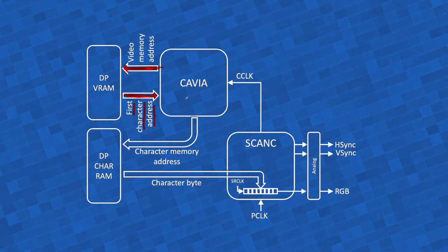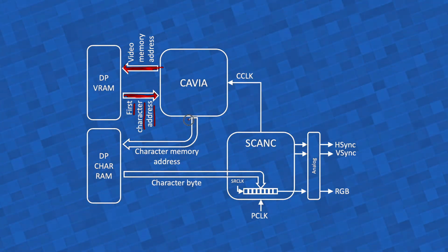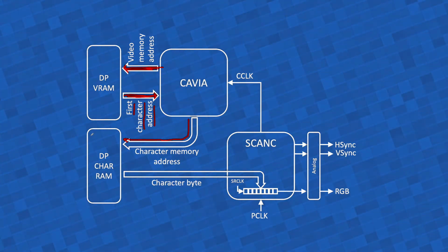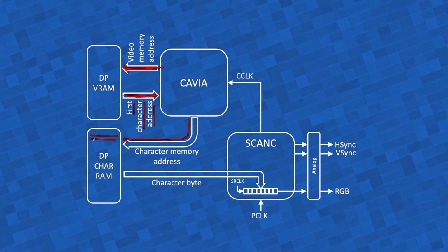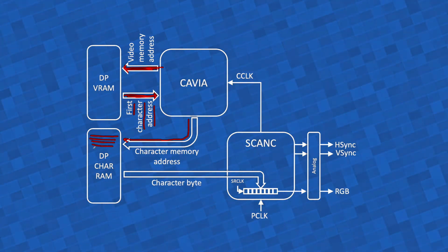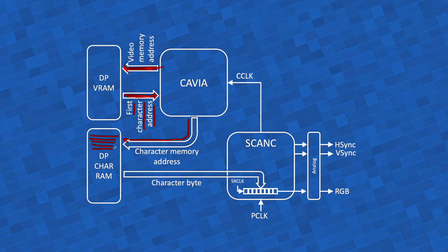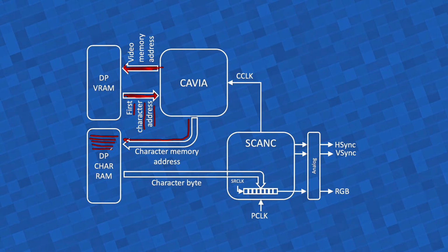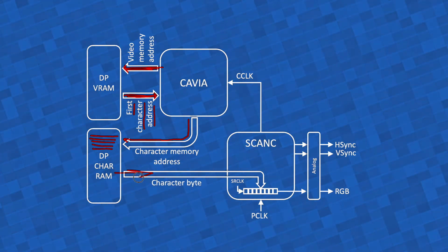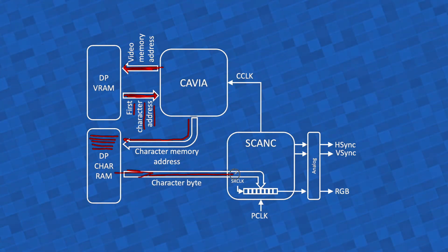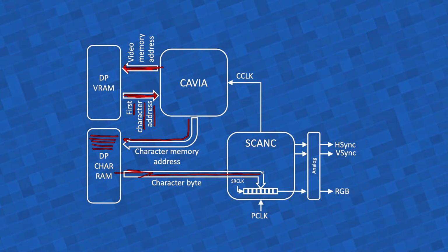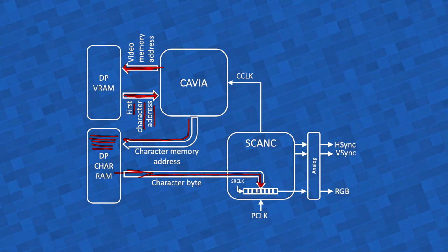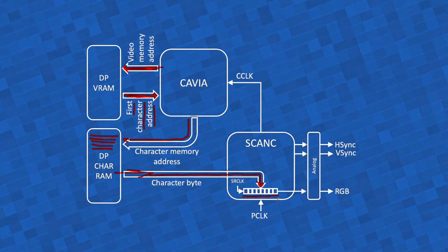And then VGA will take that, and then it will have to index that, adding from 0 to 7 to that address, so it can read out the 8 corresponding bytes of that character here from the character memory where the character definition is. Now, once these bytes are addressed here, they will pop here. So these bytes coming here will be actual bitmaps corresponding to each line of the character. They will be loaded into the shift register, like I alluded before. That's an 8-bit shift register.